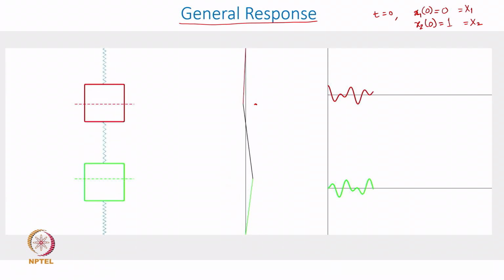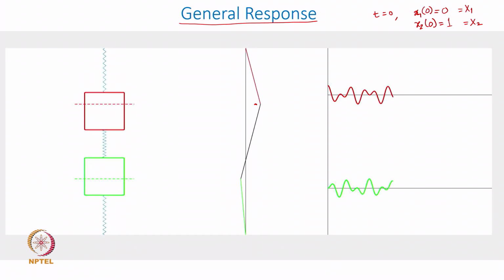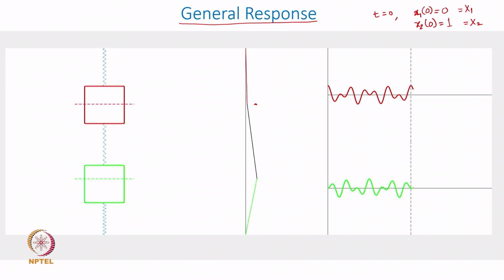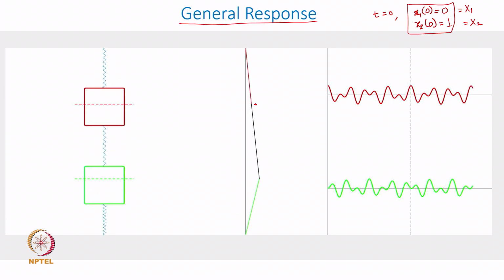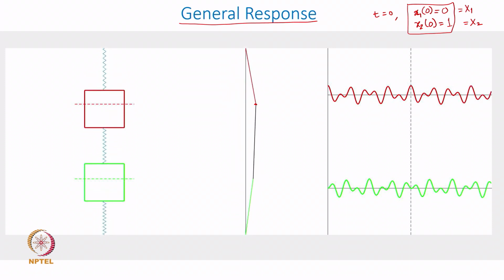You do not see a harmonic motion happening, right, and it is all because you have not maintained the initial displacement same as, or honoring, the mode shape of either the first mode or the second mode, okay. And that is why the motion that you get is a mix of the two harmonic motions, okay.